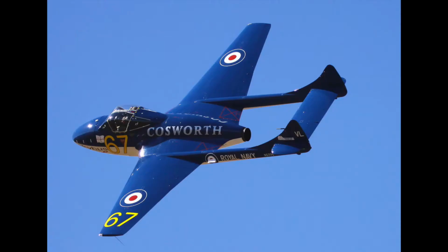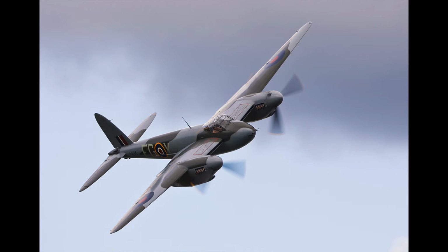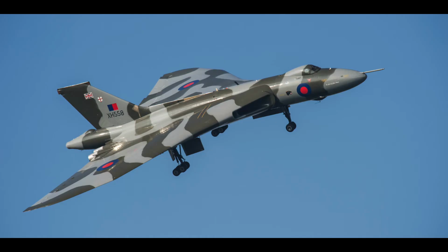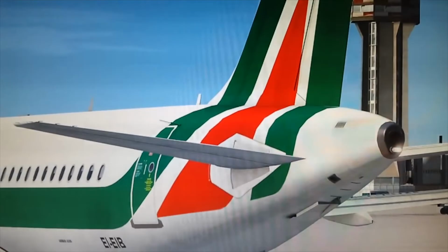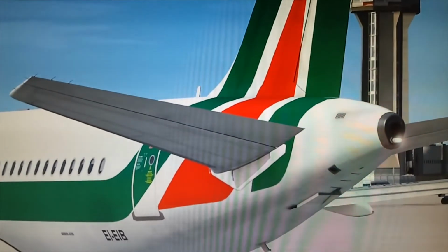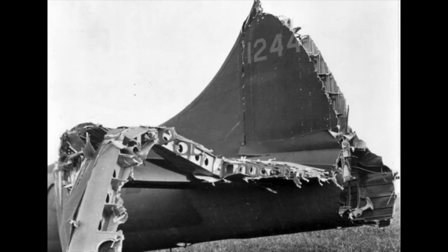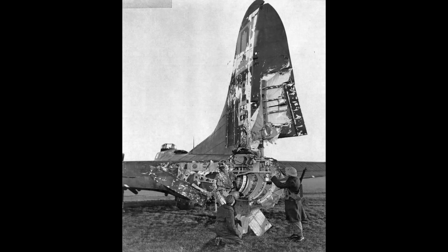Clean airflow or slipstream over these control surfaces is desirable, and propeller wash or jet thrust over the empennage gives maximum control at low air speeds. At transonic and supersonic speeds, elevators are rendered useless, and so designers came up with stabilators or moving tailplanes. Aircraft that have lost vertical fins and rudders have not necessarily crashed, but the loss of some or all of a tailplane is usually fatal.